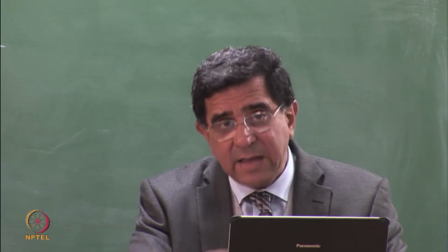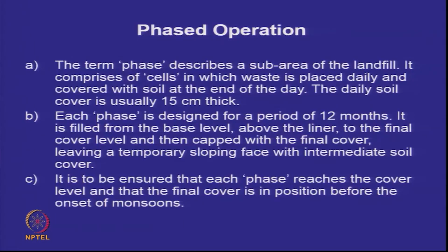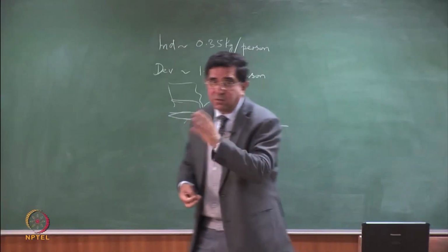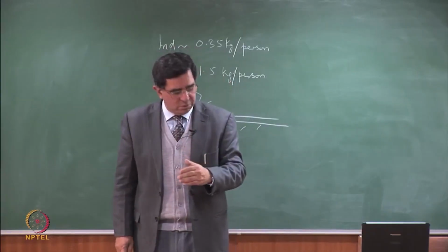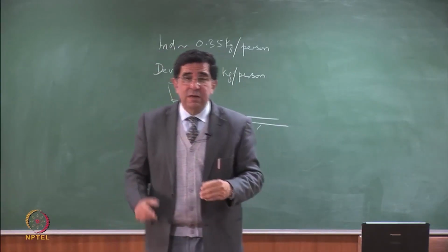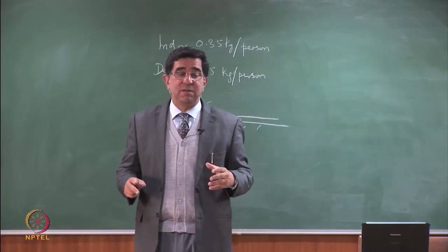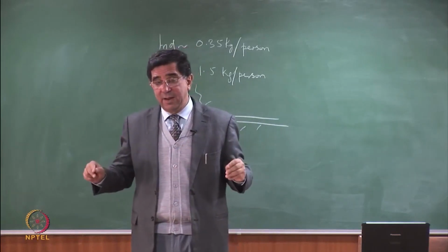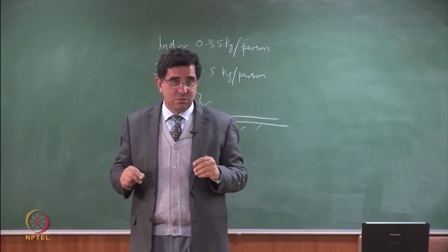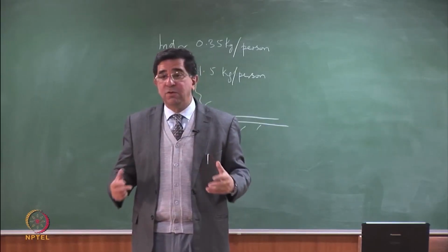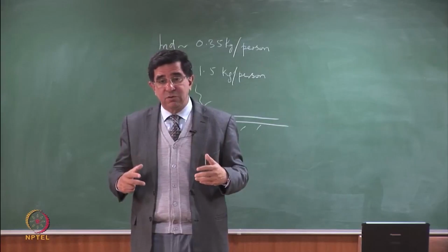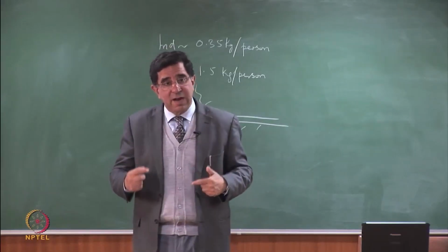The next most important aspect is phased operation. At the end of last time's lecture, somebody asked me, when do you actually put the cover on the landfill? And I said, this is the most critical question, because many people do not understand this, that you don't cap the landfill in the end. You don't cover the landfill at the end. You cover it before every monsoon. So in a country like India, we want to cover a landfill before the main rains come in. So it means every year we have to cover the landfill.